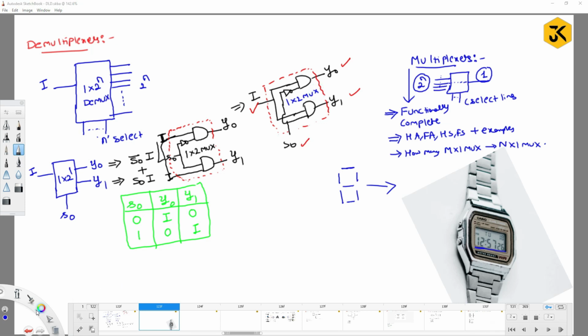Guys, if you are able to draw the circuit for a 2/1 mux, what is the respective circuit you are going to get? You are going to have basically two inputs, am I right? One is I0, another one is I1, and for both of these you are going to have one kind of NOT gate, am I right? Yes. This will be controlled by S0, and you combine these two as one line. You get the respective output, right? Yes.